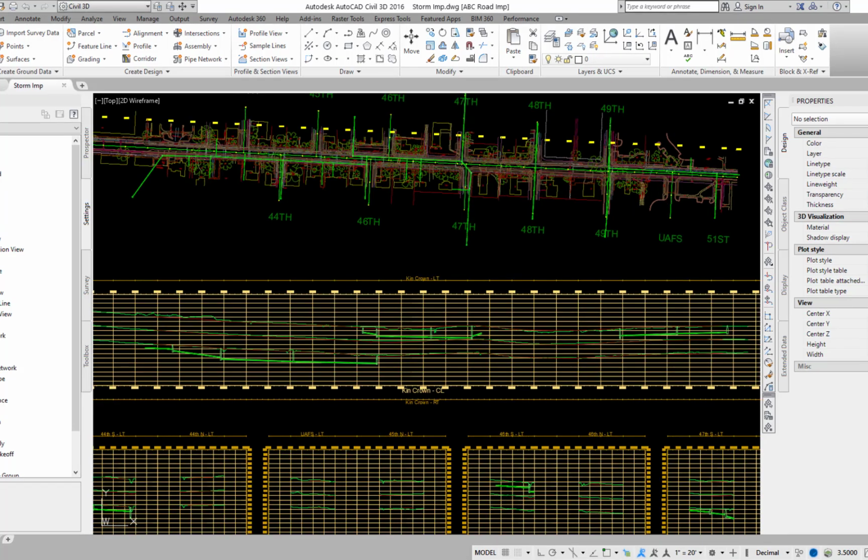I personally only use SSA for determining the size of the catchment area, the rainfall path, and the time of travel. I have found SSA to be cumbersome and time-consuming in the hydrology and hydraulic analysis of a storm drain system. This may change in future releases of Civil 3D. In the majority of cases, I use a spreadsheet I created for the hydrology analysis using the rational method, Q equals CIA. I have developed equations using SigmaPlot for the rainfall intensity duration frequency (IDF) curves and a procedure for converting the Soil Conservation Service curve number to the rational C, which are included in the spreadsheet.